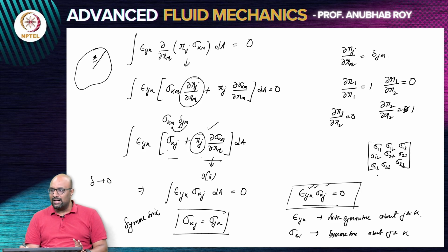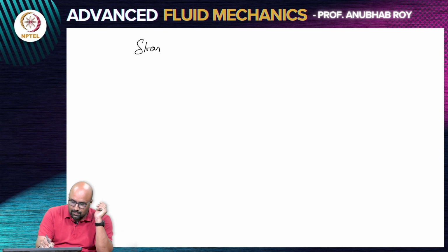This is a very important relation that you get, and this is again not specific to fluid mechanics. At this moment I have not drawn the connection between stress and deformation. That is where we will now say that this is a fluid. So this is in general true for any problem in continuum mechanics. And then you can ask a question here. Is there some assumption that I have made which will invalidate this symmetricity conclusion? We have concluded that it is symmetric. Our final conclusion is that the stress tensor is symmetric.